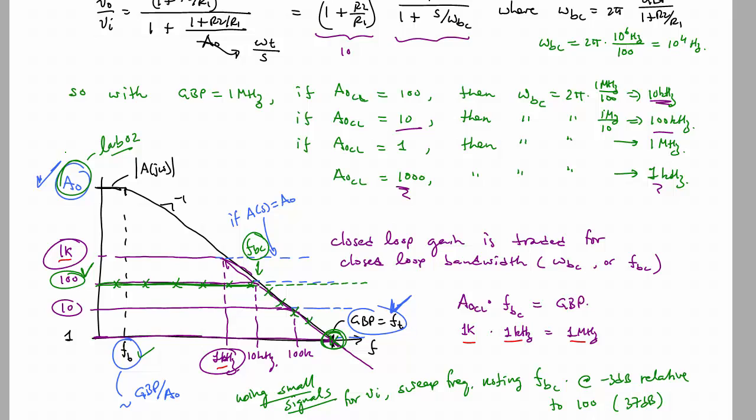So you would know A0 first, then you could find the gain bandwidth product second, and then finally you can calculate the open loop break frequency third, just by calculating, not making another measurement. And again, you get the gain bandwidth product by noting the closed loop break frequency of some op-amp circuit that has some gain. The higher the gain you give it, the lower the frequency at which that break will occur.